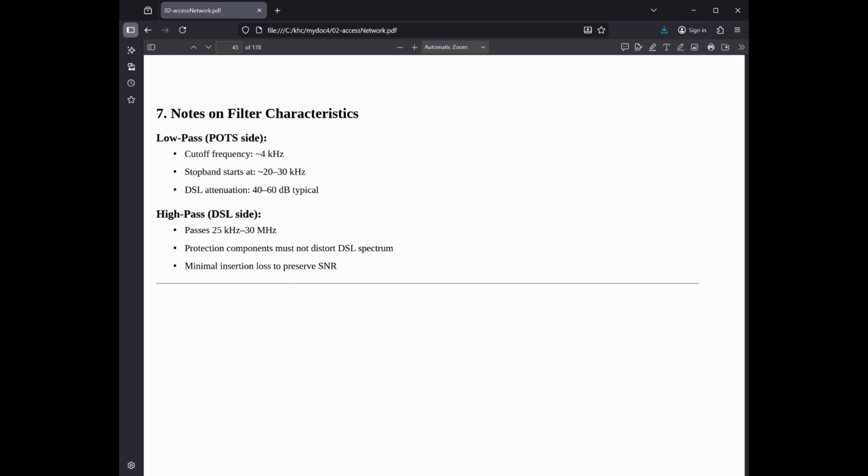Common mode chokes. These extra inductors help eliminate electromagnetic interference, EMI, and radio frequency interference, RFI, from picking up nearby radio stations or household appliances. Summary of component checklist. Component, purpose, why it is essential. GDT/gas tube: lightning/surge protection, not in basic functional models but essential for real-world safety. Ferrite cores: handle DC loop current, preventing filter failure under high electrical load. Transistors: active signal filtering found in premium splitters for superior noise isolation. ESD diodes: static protection for sensitive electronic ports from human contact.